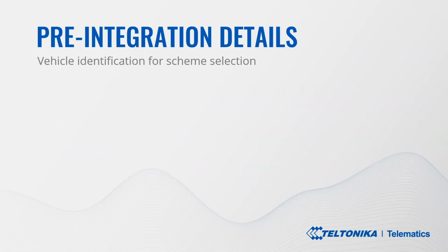Let's move on and define steps for accurate SIM selection. If you're able to determine the make year, the model, the generation, and the options of the car, it will be useful. The options of the car include a keyless option or not, electric vehicle or not, left-hand drive or right-hand drive. Different variations of the same vehicle may use separate program numbers.